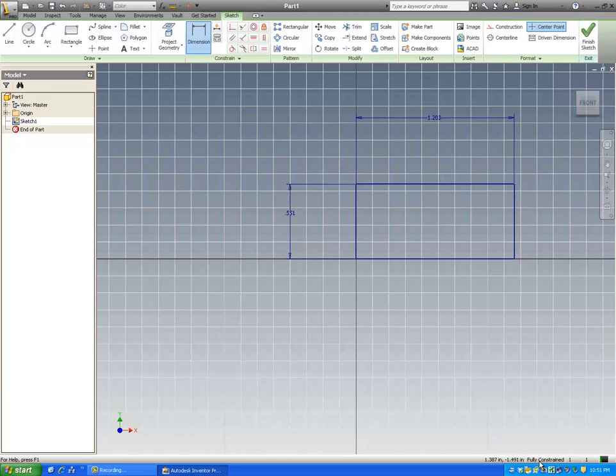Now if I notice down here, I have a fully constrained sketch now, which is very important. Once you get into 3D space, you want this sketch to be fully constrained. I'm going to make all of my puzzle pieces on units of 1. So, when you're making a 3-inch by 3-inch by 3-inch puzzle, you could have 1 by 1 pieces, or 1 by 1 by 2 pieces, or 1 by 1 by 3-inch pieces. So I'm going to start by making the height of this one.